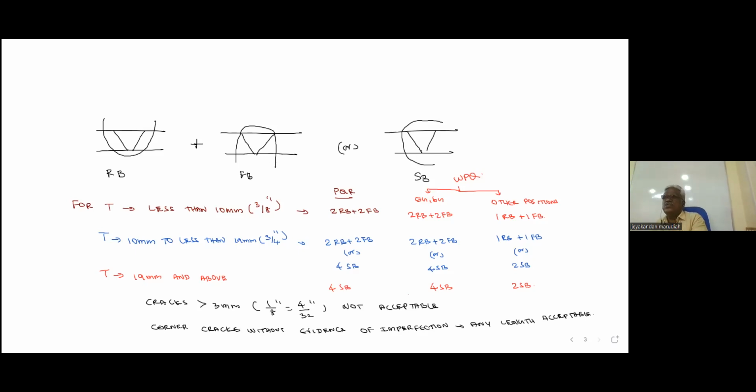Now, what should be the hardness value? If we have a stress corrosion cracking service, we have seen amine stress corrosion cracking, caustic stress corrosion cracking, the maximum hardness allowed for carbon steel is 200 Brinell hardness. Half molybdenum steel is 225 Brinell hardness. Other chromium molybdenum steel is 241. It is an open book question. No need to remember it.